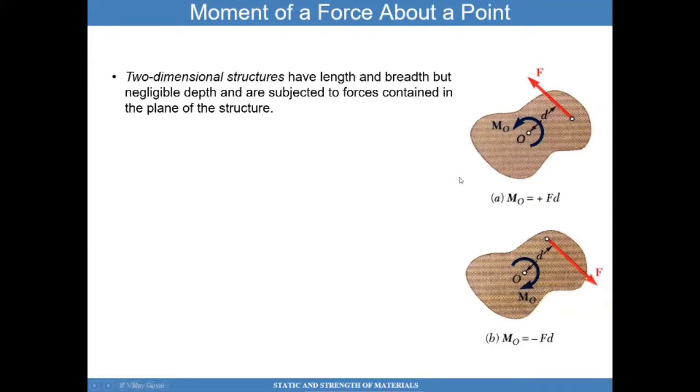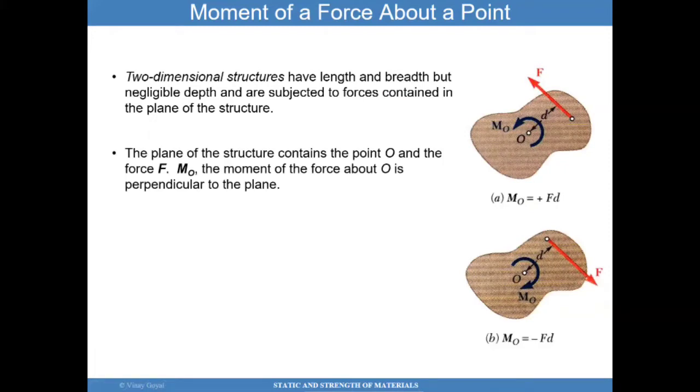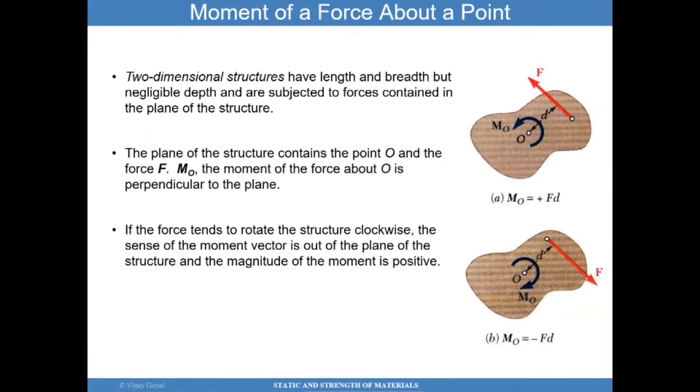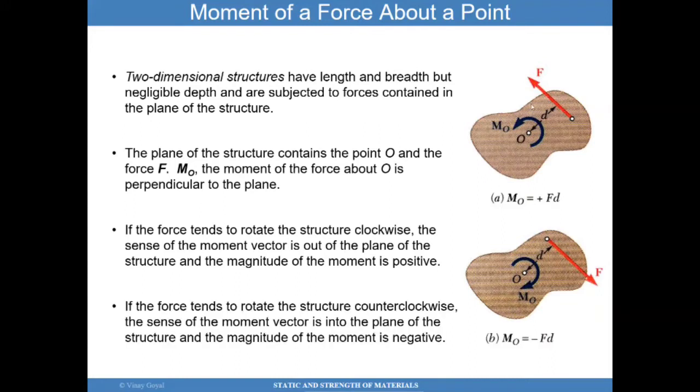That is how to calculate the moment of a force about a point. So in summary, I can take this force times this distance to calculate the total moment due to this force at a distance d from point O. Notice that this moment is acting perpendicular to this distance here, and this force has to be perpendicular to both of these.